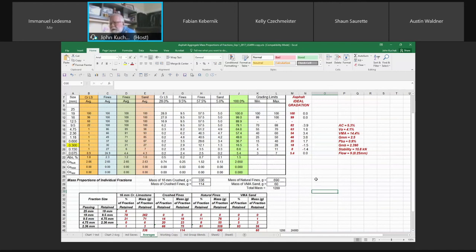Why did you increase the strength? They didn't understand that from a design point of view, you've got to have that cushion, a 5, 6, 7 MPa. You're going to fail somewhere along the line, 1%, 99% of the time you're going to make it. So they just kind of shot themselves in the foot. They created their own problem by making that concrete way too brittle.